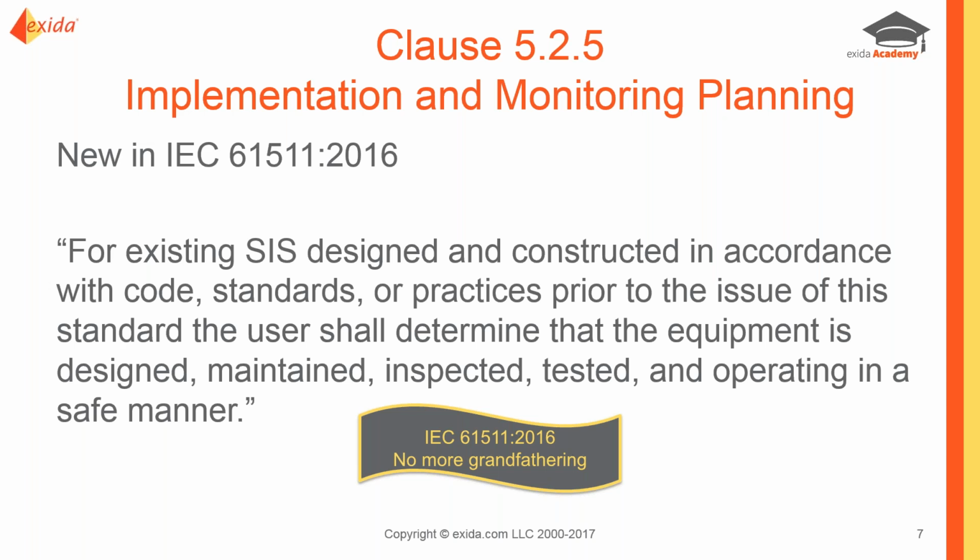In the current version of ISA 84, there is a statement of a grandfather clause. The language that previously appeared in 61511 was a little bit soft about that, so a lot of people did do grandfathering. But when this is removed from the ISA 84 clause, then obviously it means we need to implement these procedures and practices on all systems, even if they were pre-existing prior to the issue of the standard.